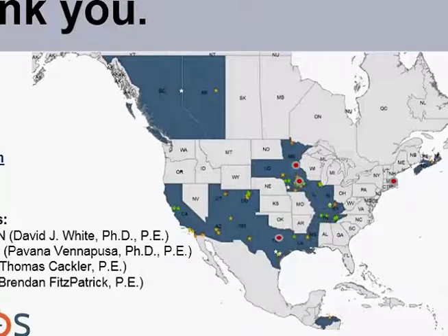So it's a little bit different reason to do the spot testing. We're pushing to use the mapping results more for acceptance and identifying those locations. You can still do acceptance independent testing, but we want to use that measurement to really help the contractor understand what the process improvement should be.